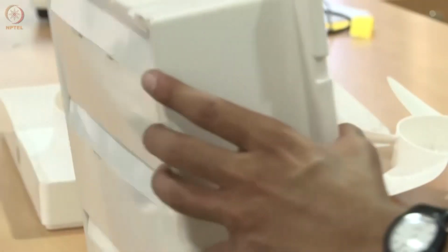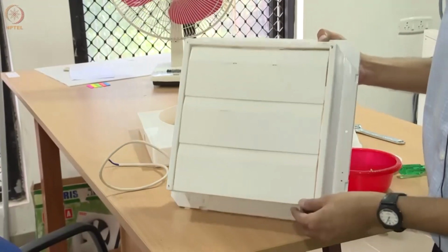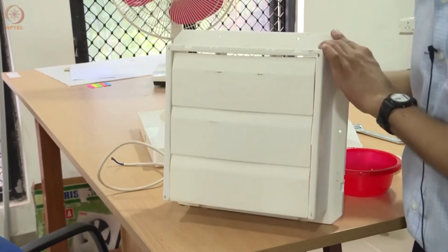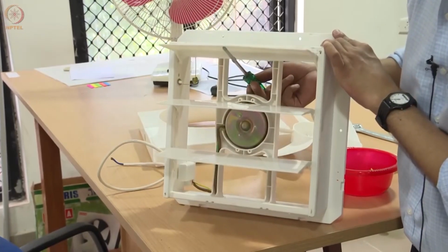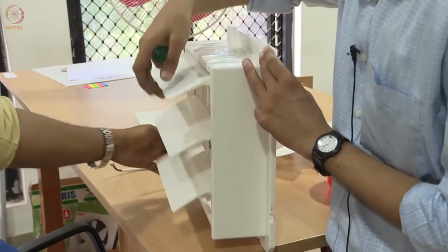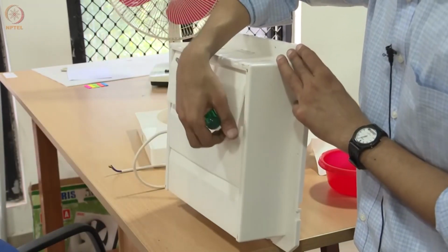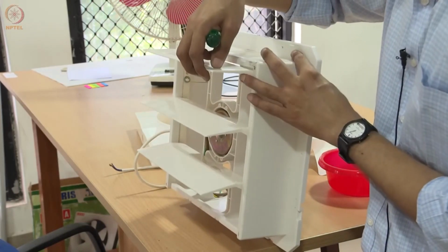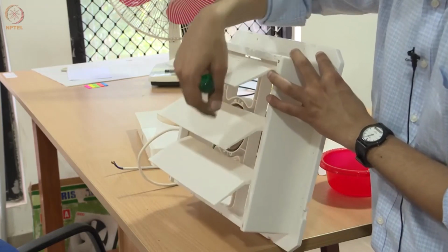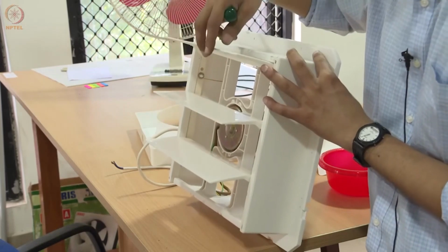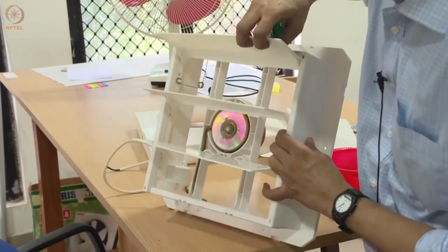Now the last part of the mechanism, let us look at how the guards automatically open and close. As I said earlier, when air flows, air pressure acts on these blades and creates a torque on these guards and then opens them. As you can see, all the guards are coupled to each other. The reason is that we want synchronized motion between all three blades. You don't want different blades moving to different positions during operation. So there is a parallelogram mechanism.